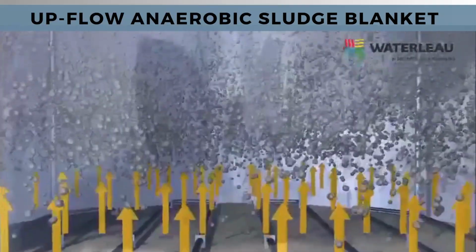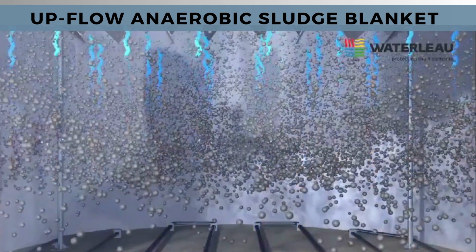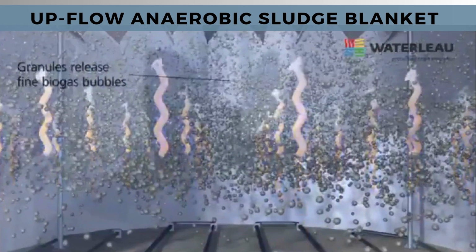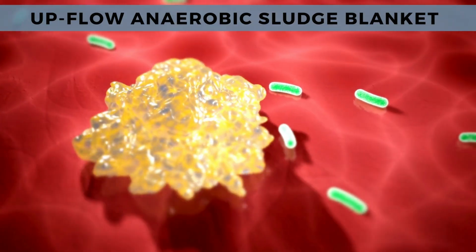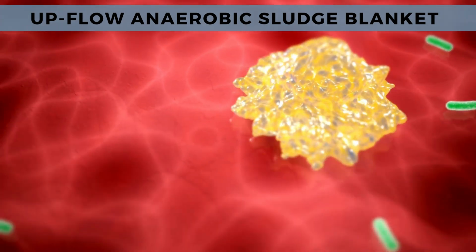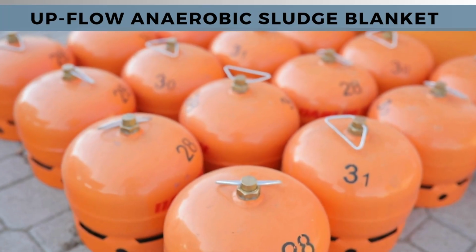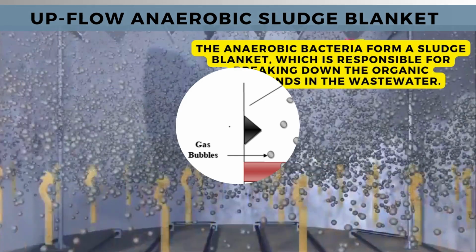In an upflow anaerobic sludge blanket reactor, wastewater flows upward through a dense blanket of anaerobic sludge microorganisms. As wastewater passes through the sludge, the organic pollutants are digested by the anaerobic bacteria, converting them into biogas, mainly methane and carbon dioxide. The system is divided into three zones, namely the sludge zone located at the bottom, the activated sludge blanket in the middle, and the gas-liquid-solid separator at the top.